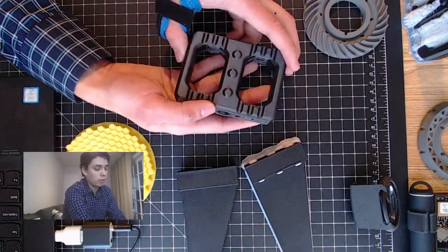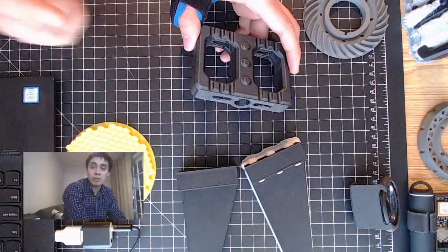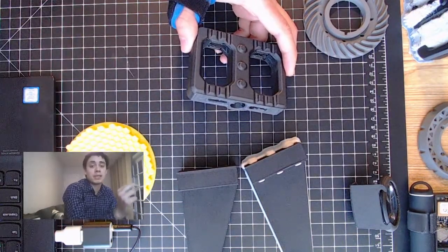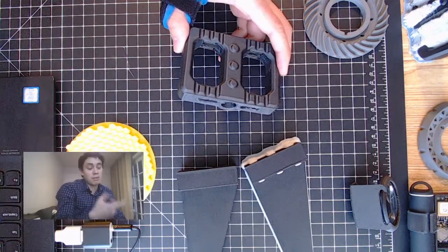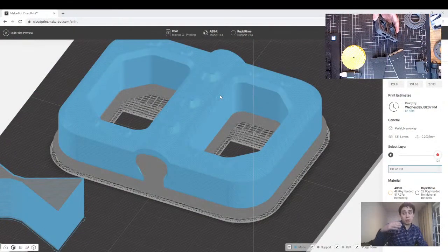way less material overall. Well, the model material will be the same amount, but in reducing the amount of support material, I'm not only saving material, but also saving time, and a considerable amount of that, right? Because as we saw here, it goes from 18 hours to about 9 hours. So almost half the time saved just by changing the part orientation.